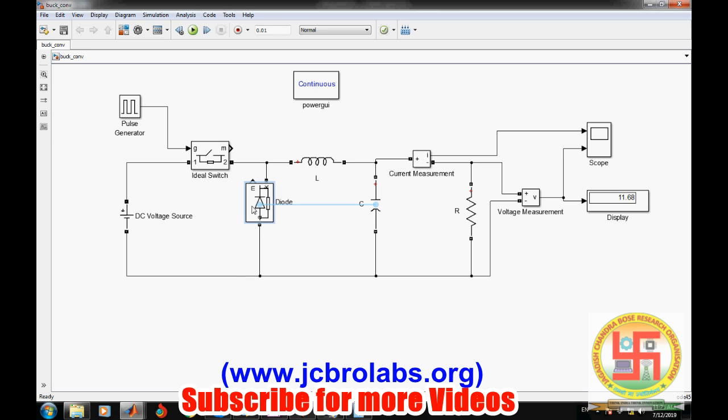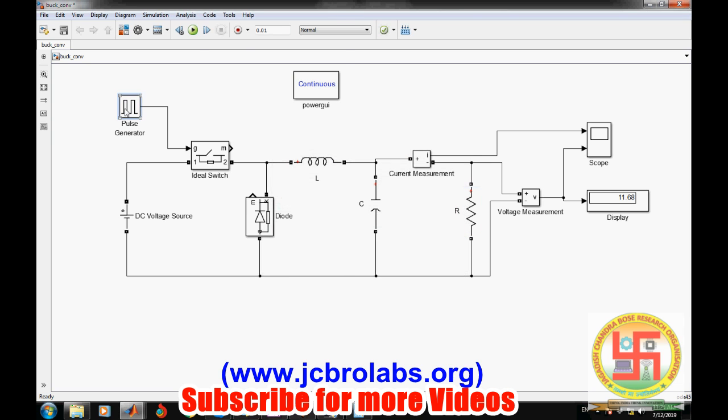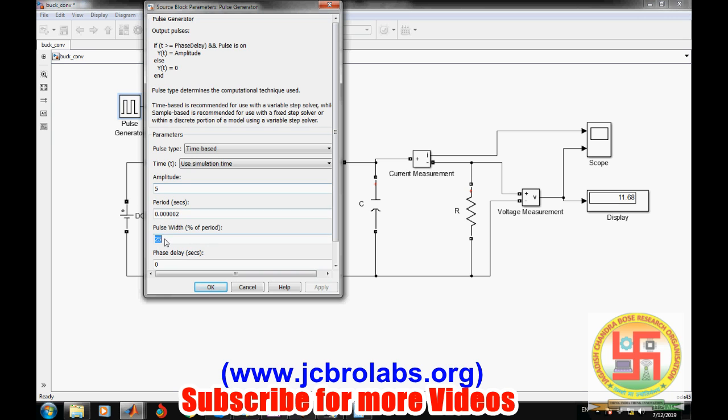Okay, we will discuss this particular concept in some other video, but I hope you understand how to simulate this buck converter and how to make it work in different conditions, and what the several conditions are which are required to make this model work properly. So let's change the value of R back to its original value, 8 ohm, and the duty cycle to 40%.